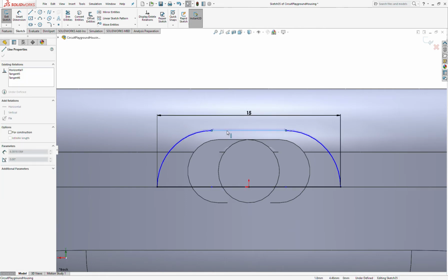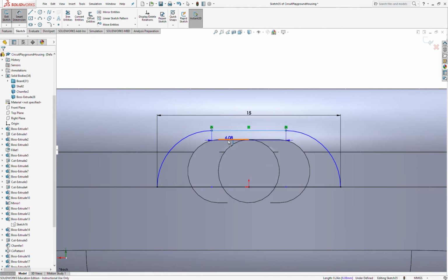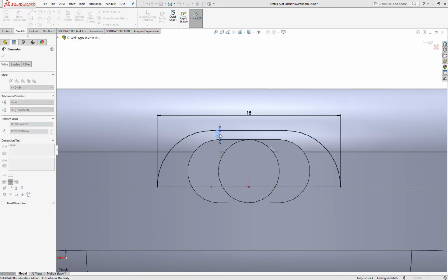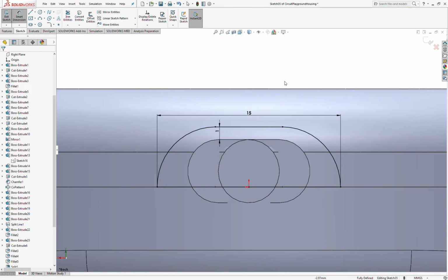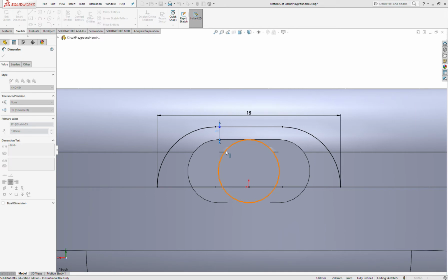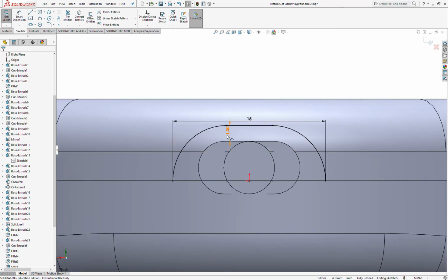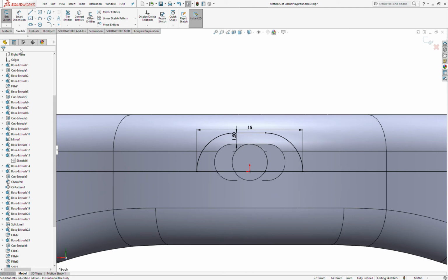Go. And then give it a height. In this case, I'm actually just going to do an offset from that cord and give us 1 millimeter. Make sure that we have a bit of material when we cut through. Maybe even a little more. Let's do 1.5. We'll be safe. Cool, so we've got this shape.